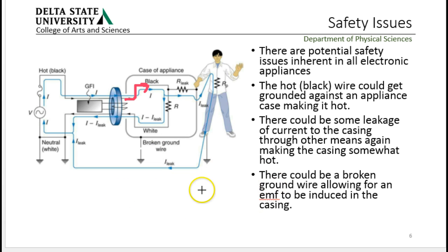If you were to go out and look around your house over by the meter, you'll find that there is a metal bar or metal pipe driven into the ground and a fairly large cable that connects that into your house. So the ground wire on everything in your house should in principle connect to the ground outside your house. The earth essentially acts as a huge, enormous electron dump. We can stick as many electrons into the earth as we want, and it makes very little difference.